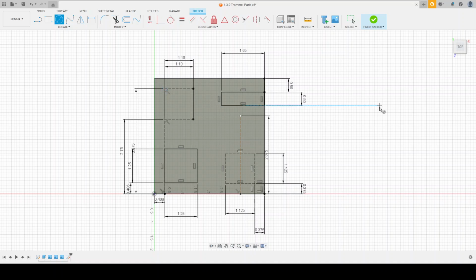At this point, again, we're not in construction type, so it'll be a full object line. The type of circle I'm doing is center point diameter. So I'm picking the point and then drawing the diameter. This top left hole is going to be hole number 1. We'll put that there. This top right, I'm going to call it out as 4.